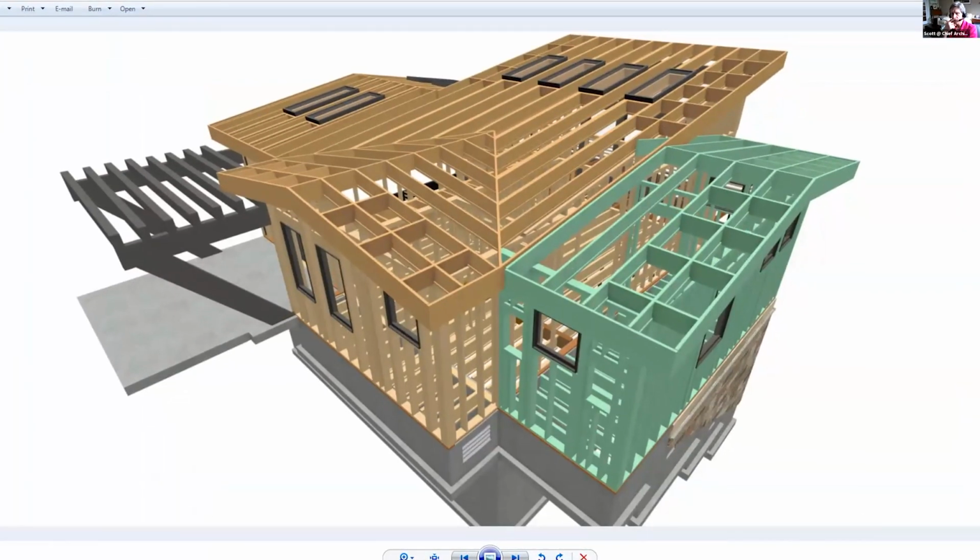Sure. If I understand your question correctly, you've got a situation where you want to do a remodel project and separate things out. Let me see if I can quickly get to a picture of this. I've created an as-built, and if I can share my screen, I'll show you what I've got. So I've got an as-built, and what I did, Rod, was color-code the remodel condition so you can see that I framed it in green. In the program, you could set those walls up as new construction, and then I can draw a rectangle or a shape around the area that I want to run the materials list for, and then generate the materials list by area, if that helps.